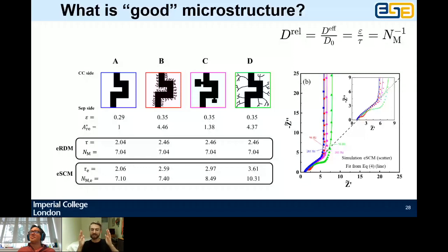Currently, you'll all have seen that on the edges of your boundaries, you might have just seen the edge of a particle, right? In reality, that particle comes off over here on the side. But all you can see at the edge of your boundary is a little sliver, a tiny thin slice. When your simulation has a mirror boundary, it thinks that thin slice is the whole particle. It thinks you've got really weirdly shaped particles.